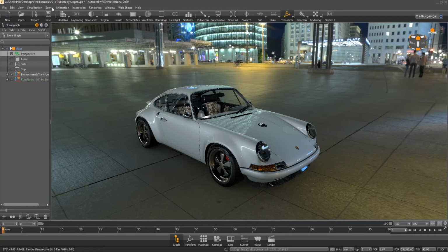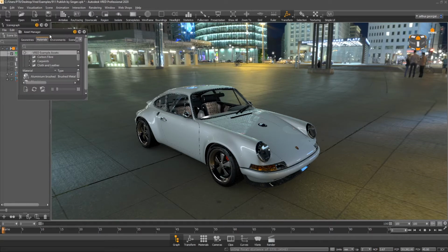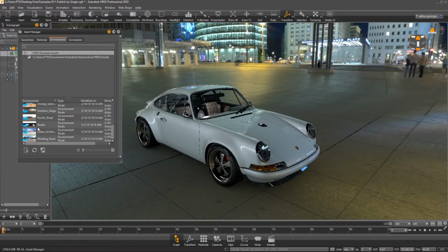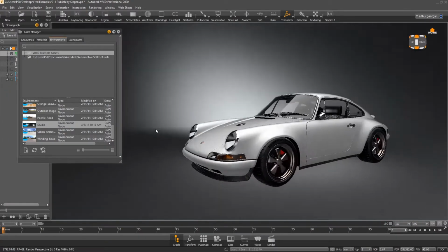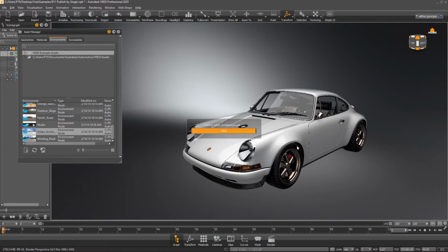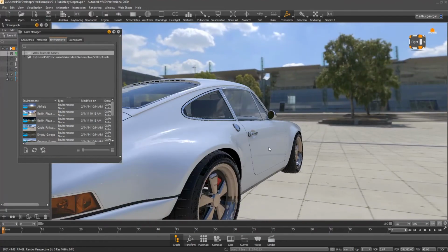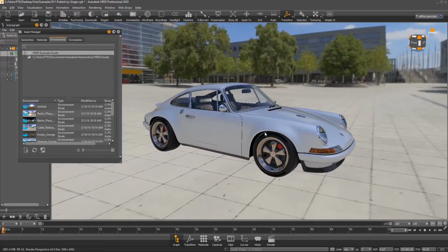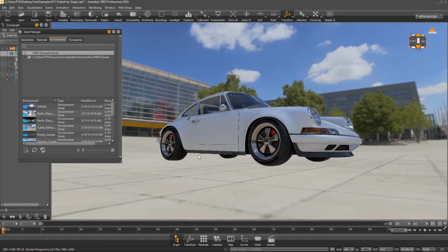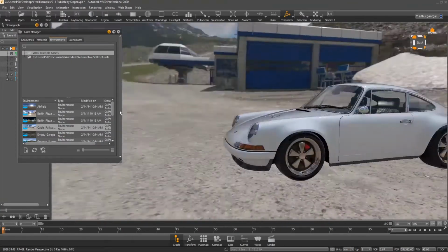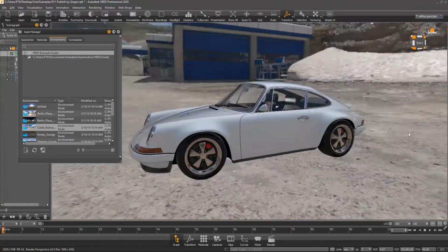Firstly, we can have a change of scenery by going to our asset manager, going over to our environments, and we get all these example environments. The basic one is just the studio, and this changes how the lighting works on our object, urban architecture, whatever you want really. There's quite a few good ones. Some tend to work a lot better with other materials, so this is coming out looking a bit dull. And of course the ground shading's gone because we've changed the environment around it. I think we've all done this in maybe Keyshot or Fusion if we've looked at changing scenery.